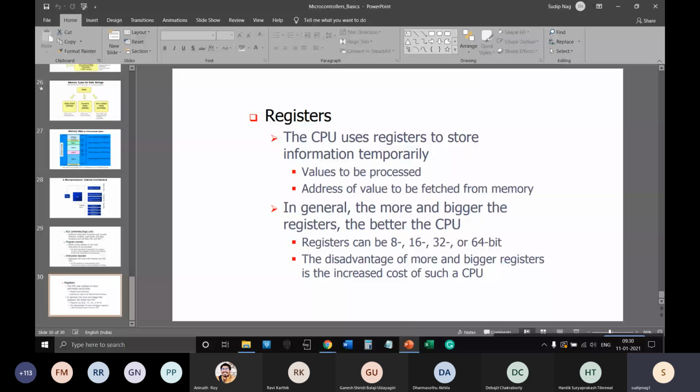Because every microprocessor that we will come across will have certain drawbacks. Obviously, advantages are there. That's why they're popular. But there are some shortcomings that may be overcome. For example, many of the modern microcontrollers are ultra low power microcontrollers. 8085, 8051, even AVR are not ultra low power. So certain variants are coming up from the AVR series and PIC series from Microchip which are ultra low power, and ultra low power uses sub-threshold digital logic.